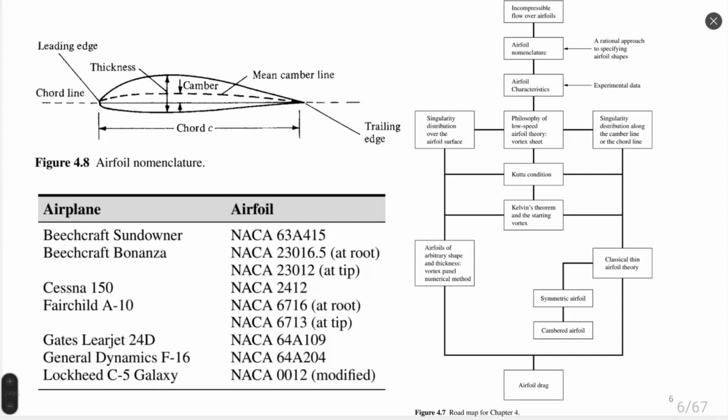Some of these parameters could be coded inside the airfoil nomenclature. Some other airfoil nomenclatures, like 5- and 6-digit, do not have a direct relation with all geometrical parameters. They have a relation with some geometrical parameters, and they can also include the lift to drag ratio or the moment coefficient at a specific point, or having just a number of an airfoil, for example, developed by companies, having just a number in the catalog.